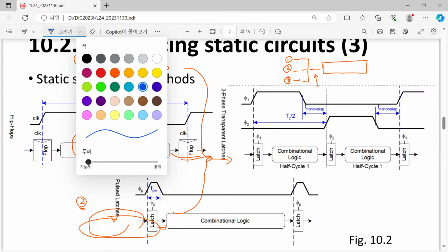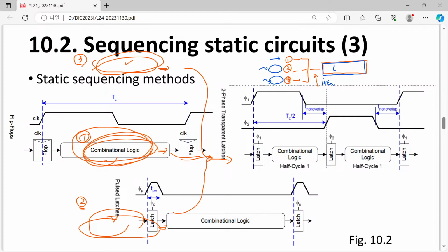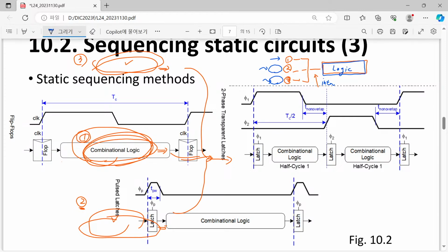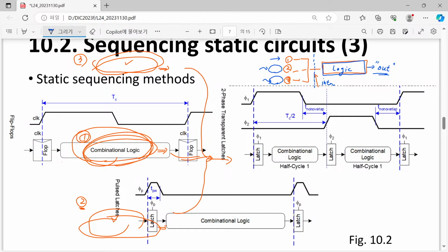Say that now the first comes, and we have to wait for the second and third signals. But before reaching the second and third signal points, there will be certain intermediate values, and these intermediate values are fed into our very important combinational logic, and it will generate a certain output which can lead to a certain decision. This is not a desirable case. Here we must introduce a certain stop.